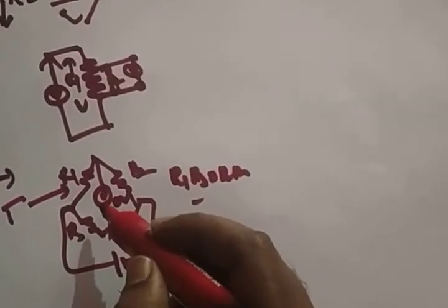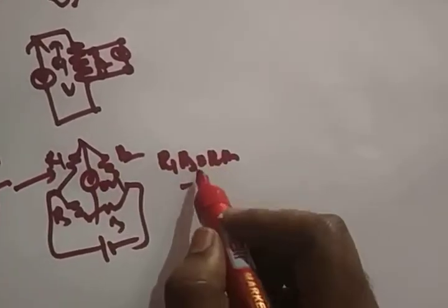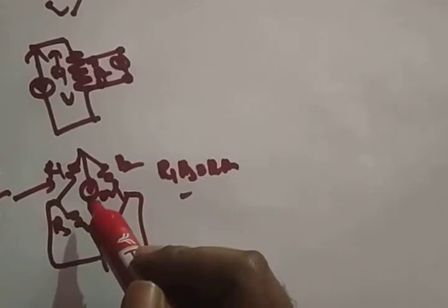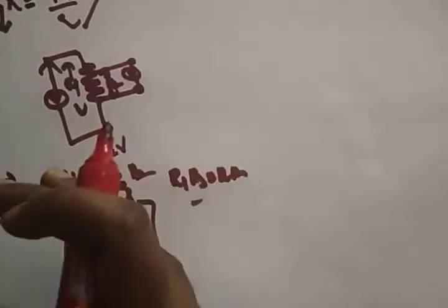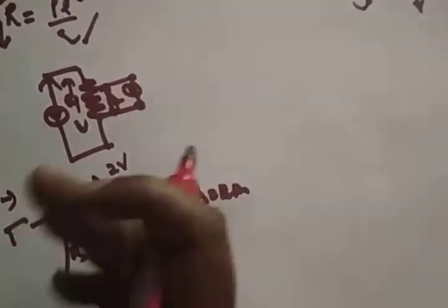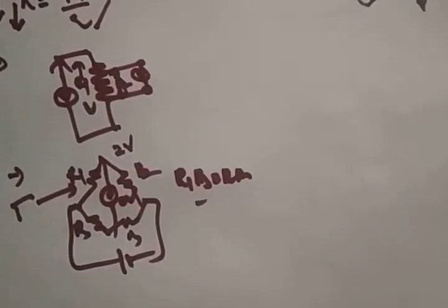If you apply temperature across this resistance, your null deflection will vary and this formula is violated. Your null deflection will show, say, 2 volts, which is analogous to the change in temperature. The temperature, a non-electrical quantity, is converted to an electrical signal through the change in resistance. We can call it a Wheatstone bridge type of resistive transducer.